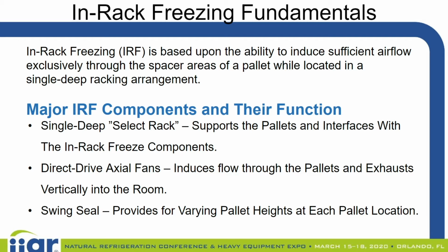So being able to target that airflow through the spacer area enables us to do a great job of liberating heat, especially from the innermost cases, where, back to our conventional blast cell, the cases on the innermost parts of the pallets tended to lag significantly in freeze performance.